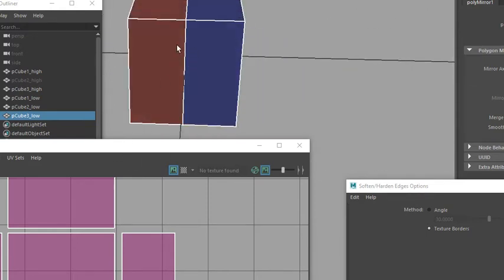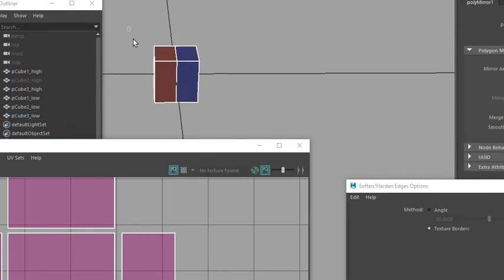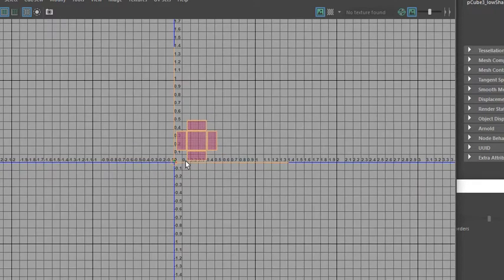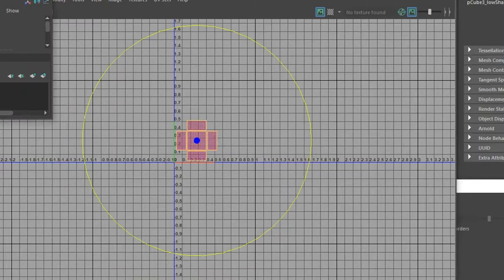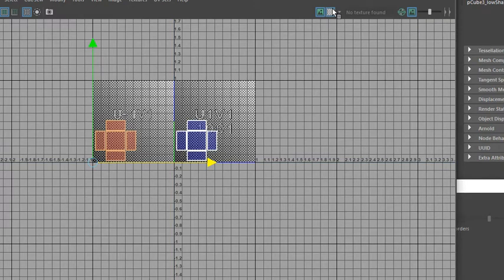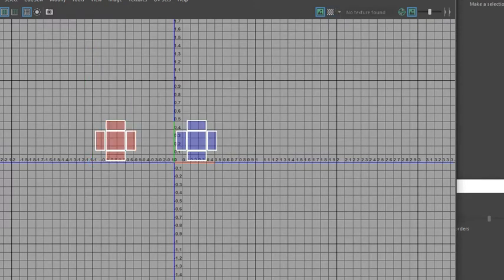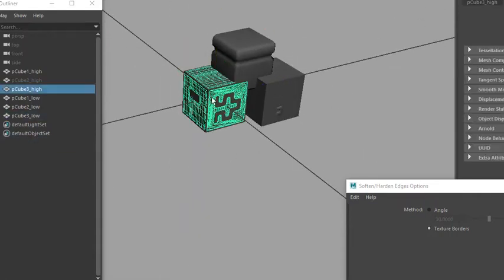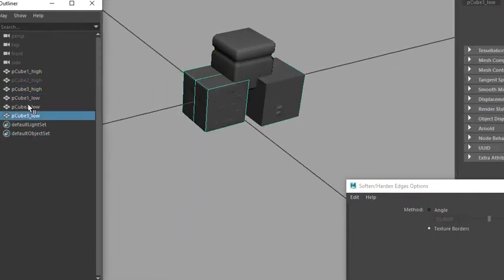And then I'm going to grab this UV sheet, this shell, and I'm going to adjust it over. So I'm going to hit W, D, X, snap that to the bottom right here. And then I'm going to shift this over one UV sheet, just like that. Okay, pretty simple. Okay, and then we should be good to go there.